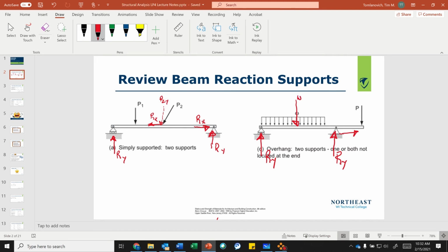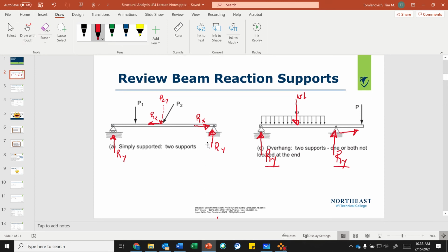This will be our line load, pounds per foot, times length. That'll turn that into a point load. And then we solve our three equations of equilibrium, basically to solve our reaction loads. We will be doing examples with that. All right, so just a review.